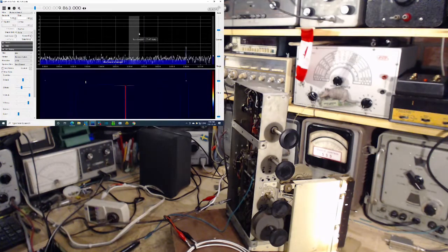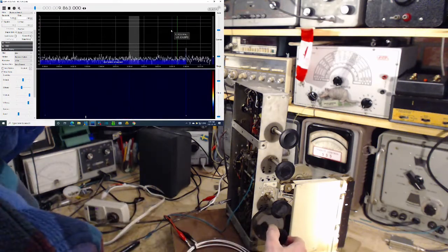So that puts this at the right frequency. You know, the SDR actually has calibration problems, which I have not taken into account. I'm gambling the SDR is accurate, but it also has problems. So now we want to move the local oscillator up there.